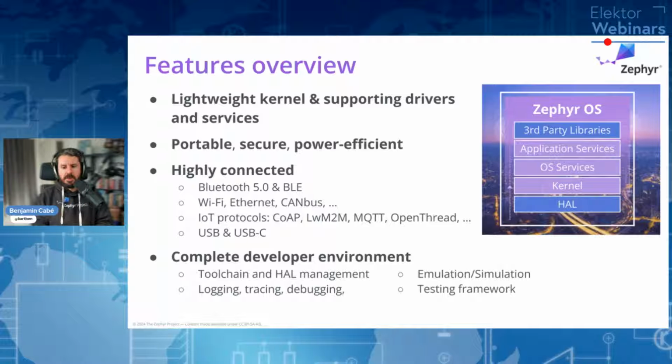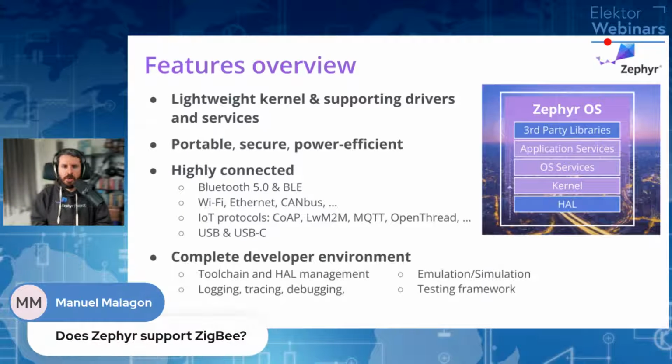So connectivity wise, if you care about Bluetooth, Zigbee, OpenThread, I mean, all those 802.15.4 based, sub-gigahertz protocols. That's one of the things where Zephyr is really, really good at, with also really good integration across the entire stack, especially with all things power management.